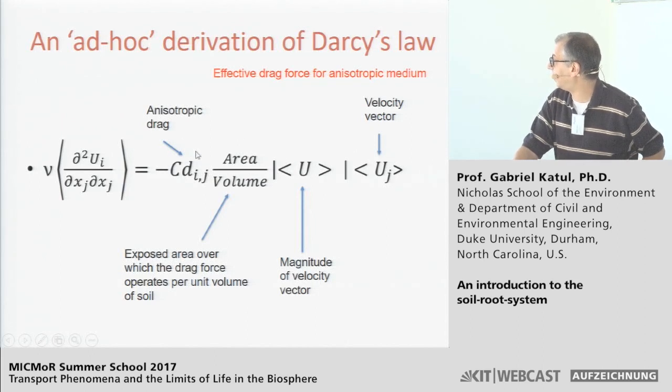This would be almost like a drag coefficient. This is the magnitude of the velocity, which is low, but still, this is what is causing the shearing between the fluid and the solid, and this would be the velocity vector. This is not entirely clean, but it's tensorially correct. With this, the challenge now becomes: can we derive some formulation for the drag?